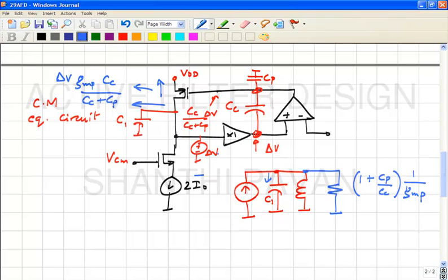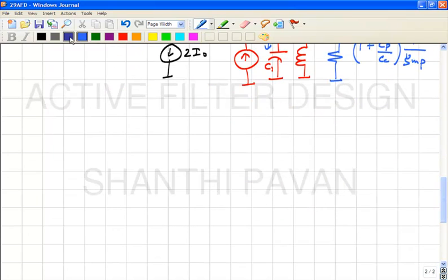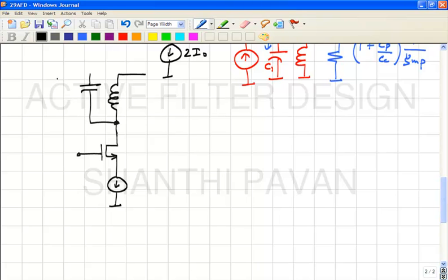So, as far as common mode signals is concerned, the equivalent network, if one were simply to quantify the change in the output common mode, if I draw the incremental equivalent, if I quantified the change in the output common mode due to a change in the input common mode, this is how it would look like.